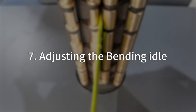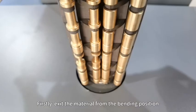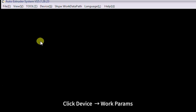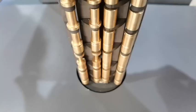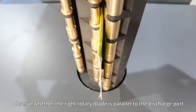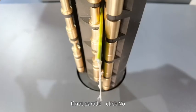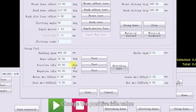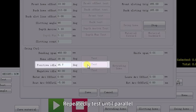7. Adjusting the bending idle. Firstly, exit the material from the bending position. Click Device, Work Params. Find the positive idle. Click Test. Launch materials. Observe whether the right rotary blade is parallel to the discharge port. If not parallel, click No. Change the positive idle value. Repeatedly test until parallel.